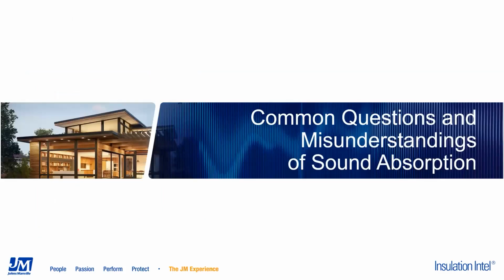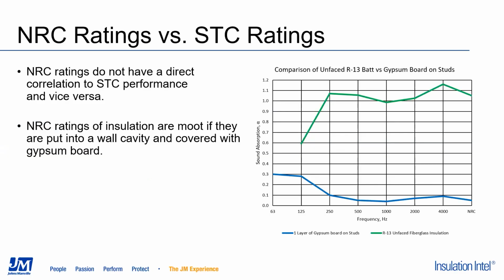And let's look at a couple of things that you may see with sound absorption. So this is also related to transmission loss, the comparison of NRC ratings versus STC ratings. If you have an NRC rating for a product, some kind of insulation that you'll be sticking into a wall cavity, it does not have a direct correlation to STC performance and vice versa. So NRC ratings are moot once you stick something into a wall cavity and cover it with gypsum board.